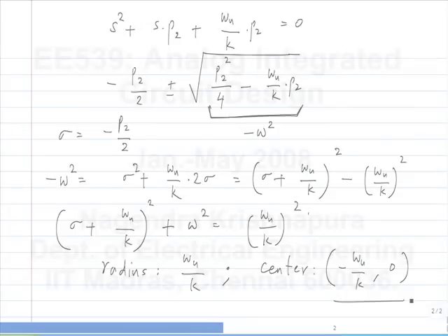But there is one sweet spot. Yesterday I showed, for the sinusoidal steady state response, that the magnitude response bandwidth can be extended if you have the pole set 45 degrees from the real axis. That is, you try to make a maximally flat magnitude response. Okay. So, any other questions on what we have done so far? Feedback systems and analysis.